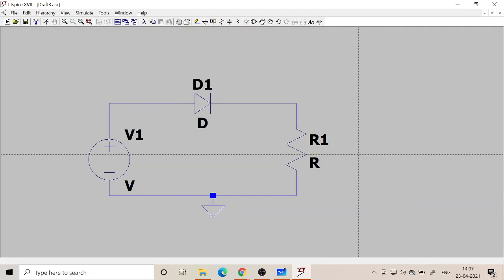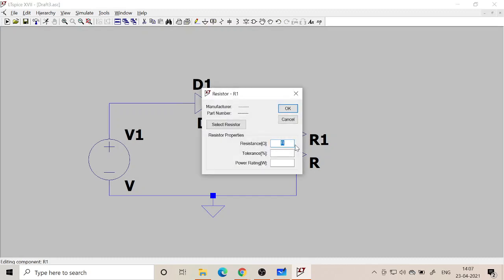So if I want to get out of this wiring mode, you right click, and then that will go, and then bring your cursor on top of the component whose value you want to assign. So you will get this hand symbol. So you right click after getting the hand symbol, then say 1 kilo. So if you want 1 kilo ohm, you write 1K.